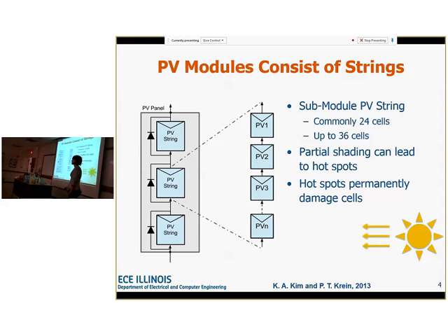I didn't have geese, so I used a duck. And he flies down, and he's just sitting right in front of your panel. And little does he know, he's causing a shadow on your panel, which he doesn't know. He's just chilling. So what happens here, though, is this one shaded PV is not getting as much light as the other ones, right? So it's like a weak cell.